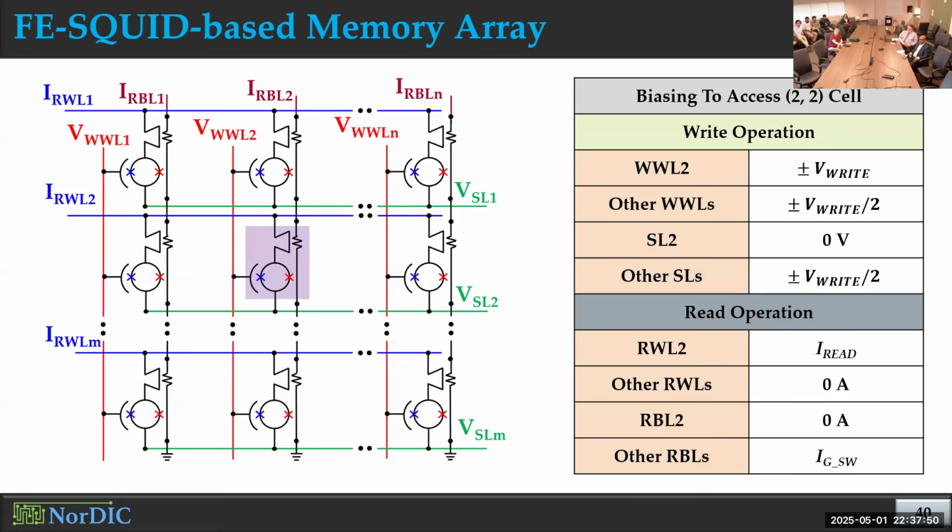Yeah, yes. There are many works who actually designed this peripheral circuitry to supply these currents that we need in different circuits, like logic circuits or memory circuits. So how can we deliver these currents? One of them is current splitter, where you apply one current and they generate multiple currents of the same magnitude. And then you can take that to different inputs of the circuits. So there are different versions of that current splitter and also similar peripheral circuitry, which you can use to apply this type of currents. But this is true, you will have higher overhead to apply this current compared to voltage biases.